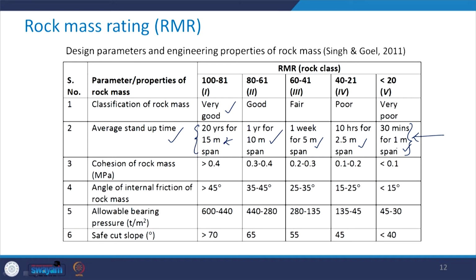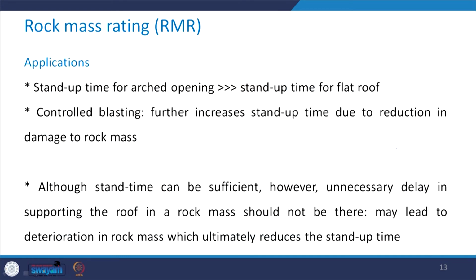Let us have some more discussion on this stand up time. The stand up time for an arched opening is much larger than the stand up time for a flat roof. What I mean to say is you can have this kind of tunnel cross section or you can have this kind of tunnel cross section, where in this case you have the arched roof and in this case you have the flat roof.